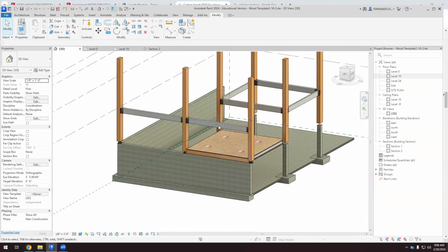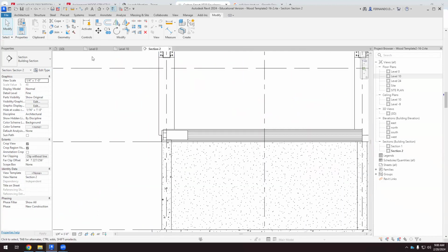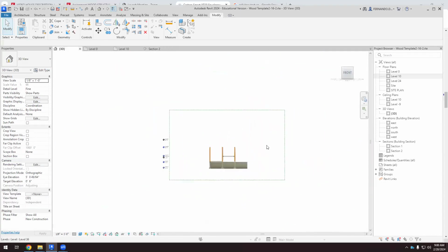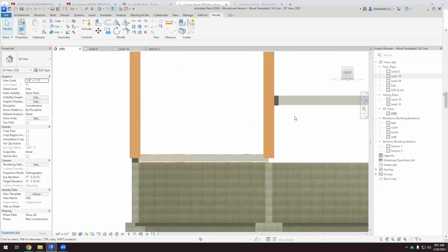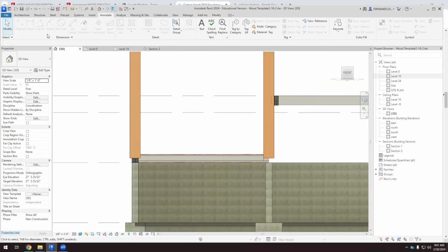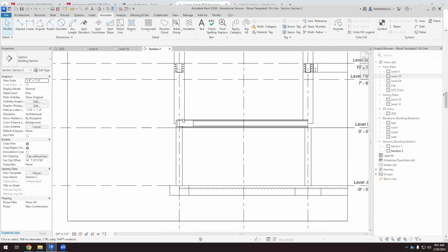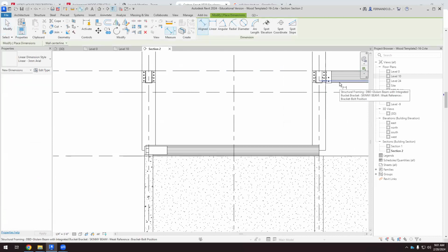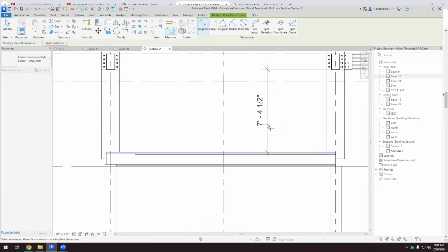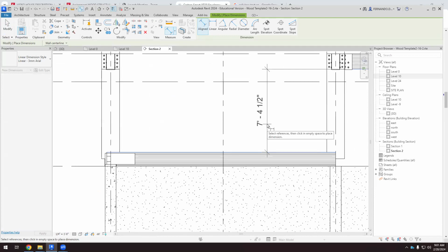Well, I told you that probably I would have to move these beams, or I would have to move the level. Okay, so in section or on this 3D view, now this floor. Okay, so look at this. If I go to annotate, no, I have to annotate in the section. So the distance between the floor, that's the floor level, and that's the beam. So the free distance is 7 feet. It's not enough. Minimum, it has to be 8 feet. But 8 feet is very low.